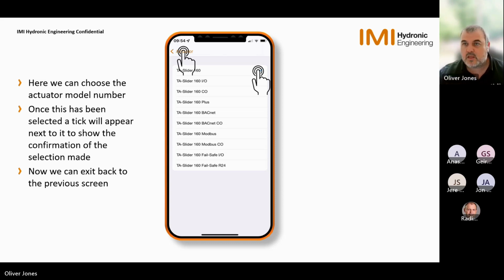So a window, if there's an actuator on the window and the window opens and you've got the heating on, that will send a binary signal back through the BMS, which then sends that to the actuator and tells the actuator to close, because there's no heating required anymore because somebody's opened the window.